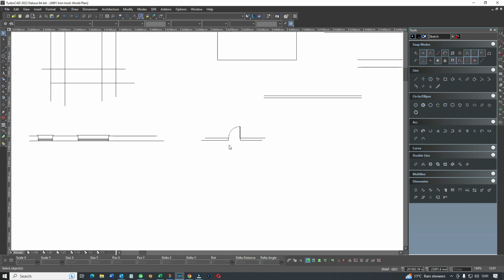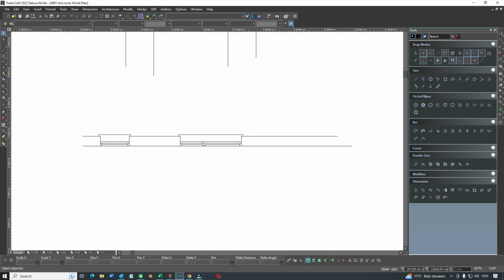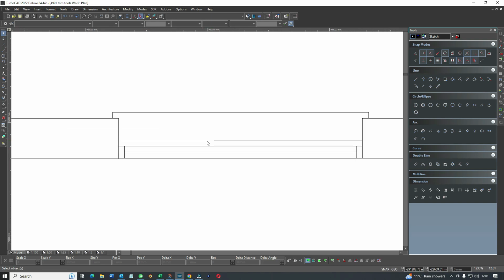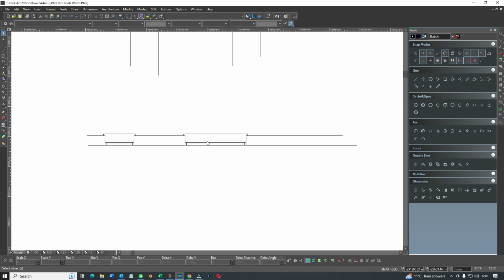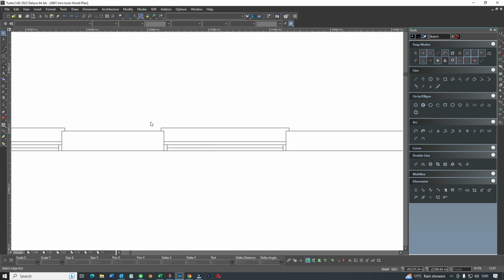This stretch tool is such an understated tool. So, for example, here we've depicted a sash window in an exterior wall. Again, it takes a bit of time. If you're doing plans for a house and they're all sash windows, you have to make up loads and loads of windows of different shapes and sizes. Or perhaps you don't, especially if you know about the stretch tool.